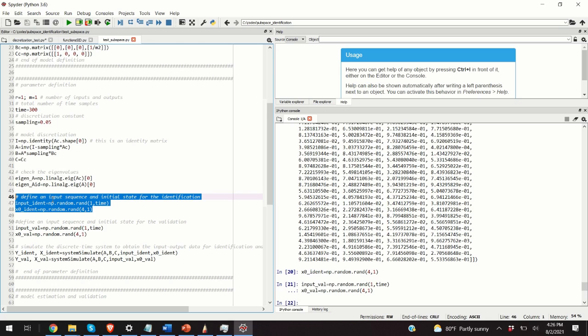Well, I can simply simulate the estimated model, and I can basically compare the simulation results of the estimated model with the data sets that are being used for system identification. And usually this will provide a very good match, since the data is being used for system identification, so the model will somehow be based on such data. This is not a good procedure.